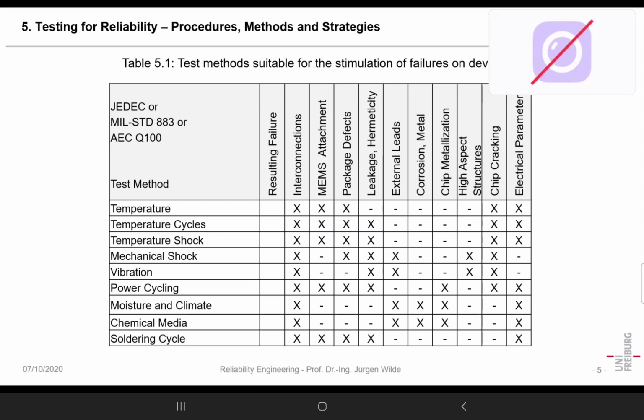Finally, the analysis found that there are certain effects like temperature, temperature cycles, temperature shock, which all are more important in, let's say, the operational phase. We have mechanical shock, which means you often drop it, or you have installed something in, let's say, a Jeep, for instance, and it's a bumpy road, and that leads to shocks. And at the same time, we also have vibrations.